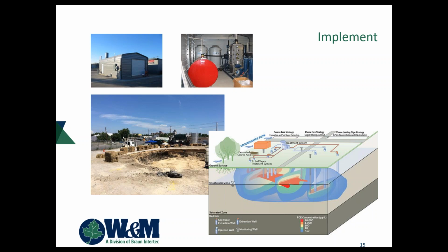hollow stem augered, or actually solid stem augered on that site, some 5 and 6 inch holes, and pneumatically fractured with liquid nitrogen to open the formation up. It sounds like a shotgun going off, even though it's 12 foot down. You kind of feel a little rumble in your feet, and pow! It's pretty cool.